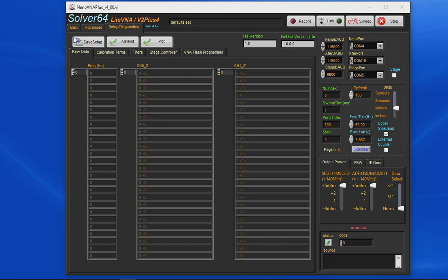I actually had somebody write me once and they were saying that my software was having all these issues. I don't know really what they were trying to do with the software, but the software is trying to communicate with the M drive motors. So of course those M drives, if you don't have those attached, the software isn't going to be able to communicate with it. What you want to do is deselect this stage if you're not going to use those M drive motors. To date, I don't know anybody that's actually set those up.